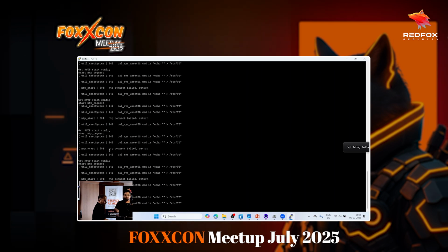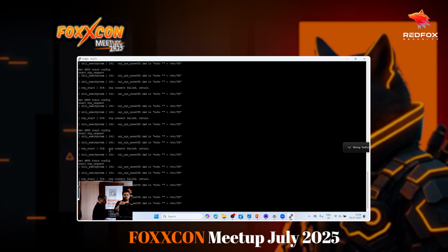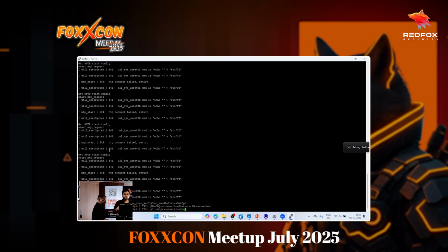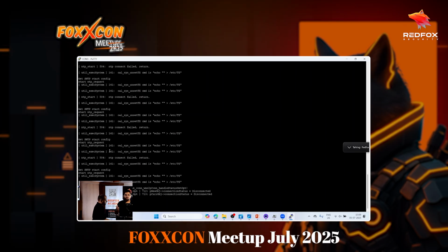There's one more thing that you could do to block UART. You could block UART write. You can get read out of it, like I was showing you logs in the beginning. You could do that. Logs tumko dikh jayenge, but you will not be able to type in commands. You will not be able to get this shell. And apart from that, you could just directly remove the pins. You could jumble the pins up. There's a lot of things you can do.